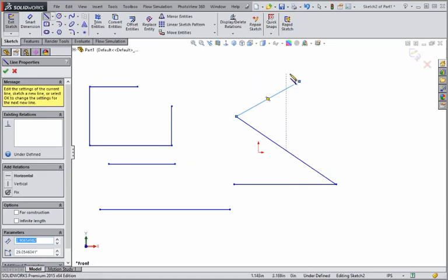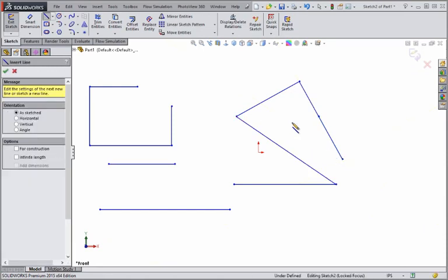For example, if I start a new line from a point on an existing line and move my cursor away at a near right angle, the perpendicular inferencing line appears and my cursor snaps to it. And a linear inferencing line appears when I move my cursor in line with the segment. Blue inferencing appears when my cursor is aligned horizontally or vertically with an existing point or endpoint.